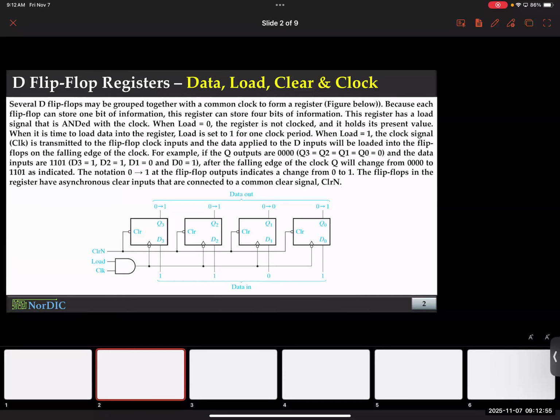First, we will talk about registers. I already told you that registers are essentially a bunch of flip-flops working together. One flip-flop can hold on to just one bit of information, but if you need to handle, say, 8-bit, 16-bit, or 32-bit numbers at a time, you have a group of flip-flops and you call them a register. So 8 flip-flops working together is an 8-bit register.